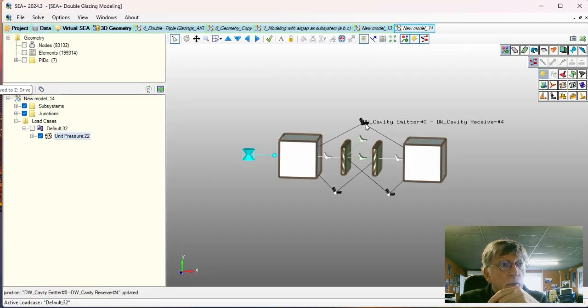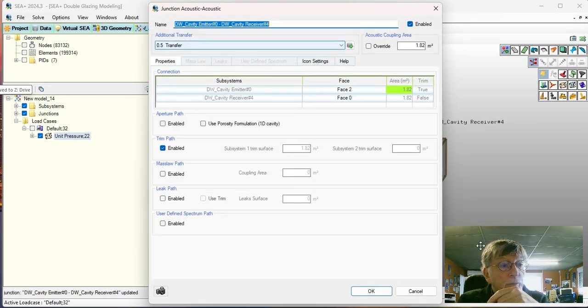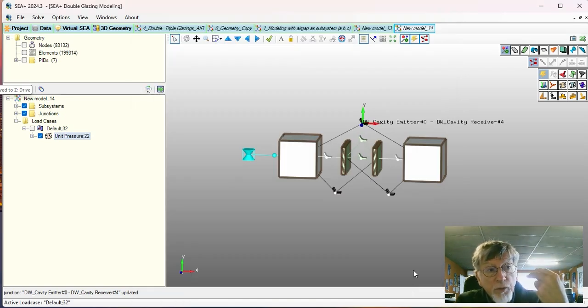In that case, I put 0.5 here, which is to say, okay, the total number of modes that contribute to the transmission is only half of the number of physical modes. Of course, I could also correct other coupling loss factor, but it's mainly acoustic transfer through the air gap, which is predominant, and it is condensed in this dominant path. So it's not necessary to think about the other coupling.